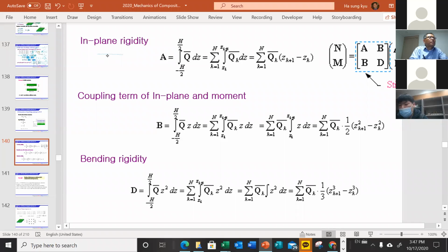plies, right? We have many plies, and say this is z equals 0, and from here to there the total thickness is h, and here is z equal h over 2, and here is z equal minus h over 2, and a certain ply. This one has the sigma bar and Q bar and epsilon bar.